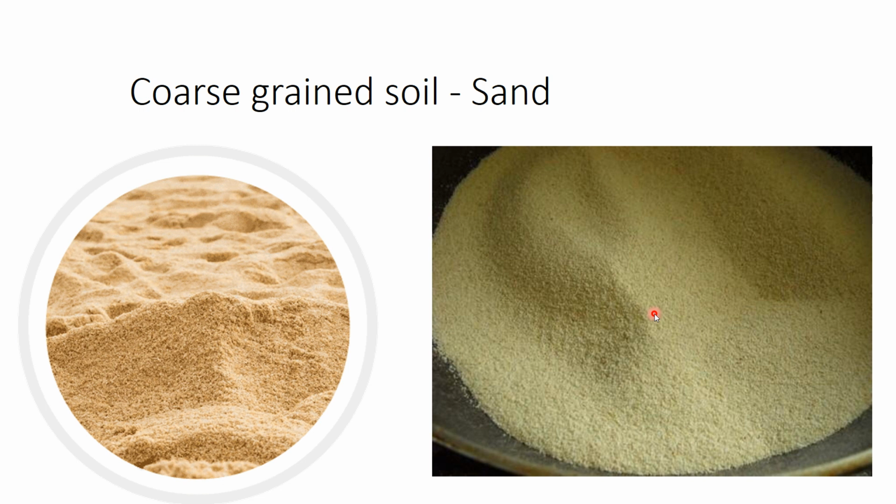Always in soil mechanics we bother about three things: permeability, shear strength, and settlement. These three are the engineering properties we talk about. When we go for a ground condition, we will analyze whether it has good permeability, whether it has a good shear strength, whether it has less settlement. Those three properties we always look after. So when it comes to sand, it will exhibit all these three properties in a very good manner.